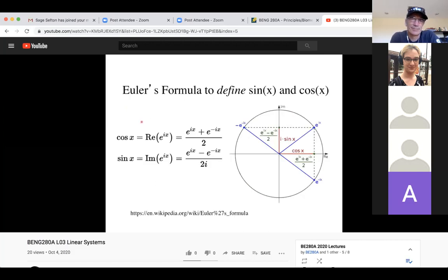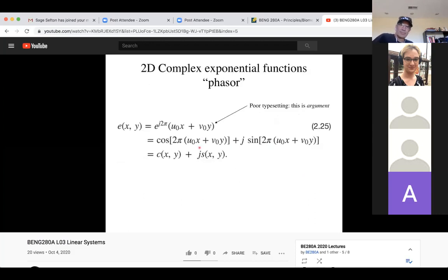You can do it in reverse and say that cos of an argument is just the real part of e to the j theta. So this equation is equivalent to cosine, and the sine term, you just pull out the imaginary component of e to the j x in this case, and this is equivalent to sine theta. So it's sort of the reciprocal function. And we'll see that there are cases, for example, when we derive the sinc function, in the integral that we derive the sinc function with, this term comes out as sine theta, or sine x. So get to know Euler's equation.